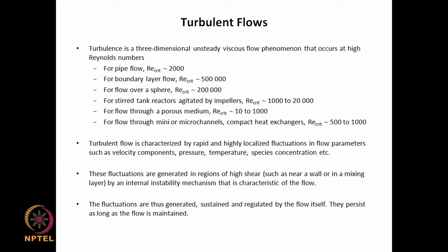Okay, so that's pretty high, although we don't expect it, and people expect this transition to be more like 50 or 100 or a few hundred. But around the Reynolds number of 50 to 100, the transition is from a steady flow into an unsteady flow leading to vortex shedding. So that vortex shedding type of flow exhibits some characteristics of turbulence, but it is not really turbulent flow. One would have to increase the velocity to a very high value such that the Reynolds number goes up to about 100,000, 200,000 for turbulent flow over the sphere to set in.